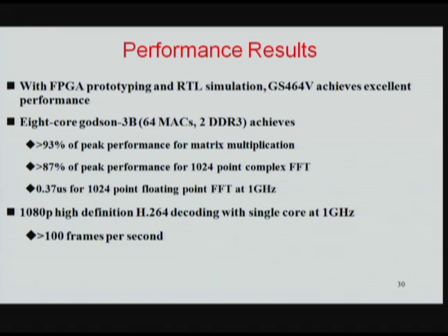With FPGA prototyping and RTL simulation, we found that they achieve excellent performance. In the 8-core Godson 3B, each core has 8 MACs, so 8 cores have 64 MACs. We only have 2 DDR3 controllers. It achieves 93% of peak performance for matrix multiplication, 87% of peak performance for 1K point complex FFT, which means with 8 cores, we can achieve 0.37 microseconds for a 1K point FFT at 1 gigahertz.